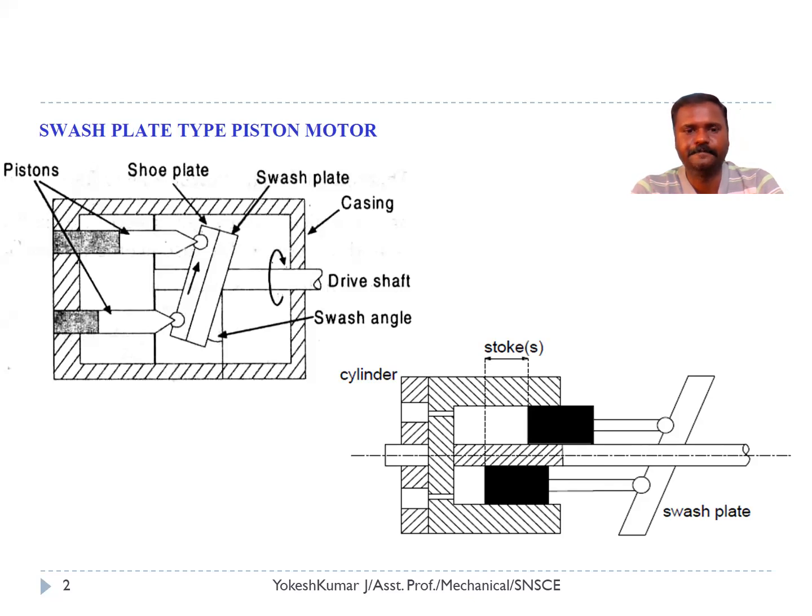power in the motor. This type of motor is suitable for slow speed or moderate speed applications in hydraulic systems, used to develop mechanical power for various applications. The drive shaft is connected with the load, and the load is rotated with the help of the drive shaft. The direction of rotation of the motor can be changed by changing the input and output. And the pressure of the motor can be changed, so that the torque of the motor is also changed.